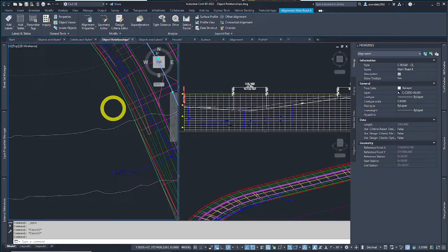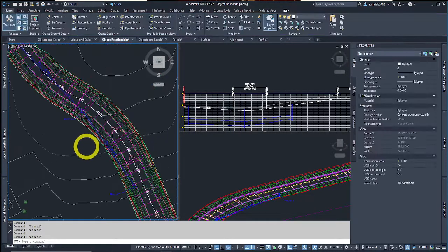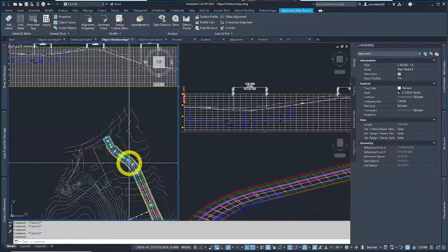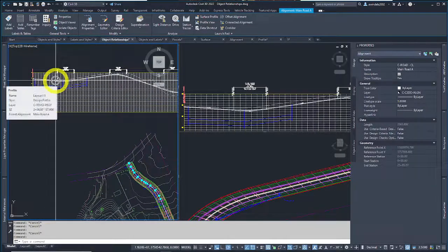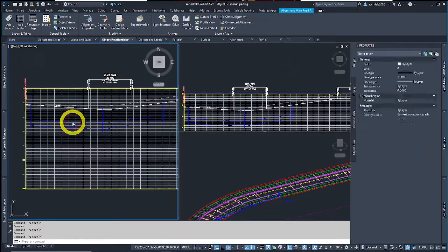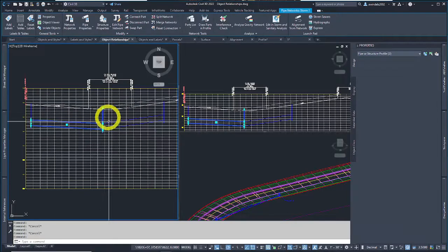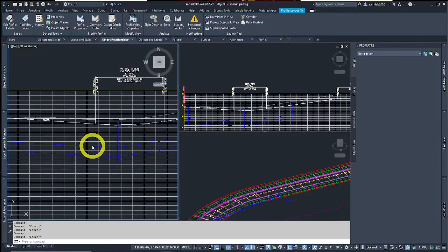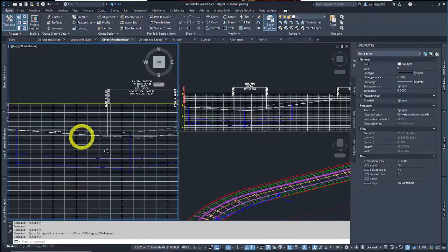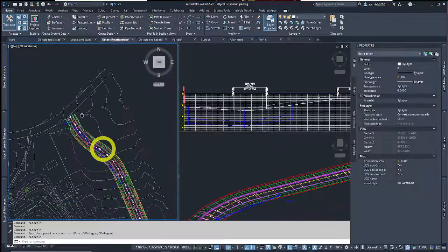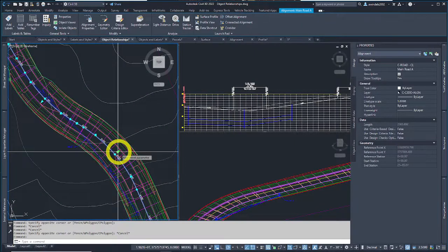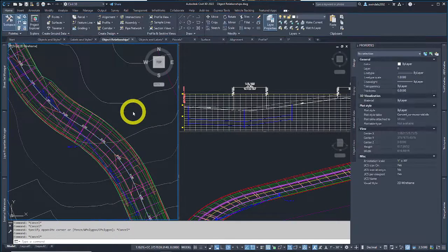So going into page 27, it's saying if the layout of the centerline needs to change for some reason, which happens a lot, all these objects are dynamically linked. So this whole grading area and also this object, this alignment, is tied to this profile, which is its vertical component, which is also tied to this Civil 3D object, this storm system underground. So this is our finished grade surface. This is where it will be designed to. This is underground stormwater utilities underneath it. Here's the grade of that surface. These are all interlinked. So if one thing changes, labels, everything is going to change with it. So I'll show you quickly how that works in this next example in 27 and 28.